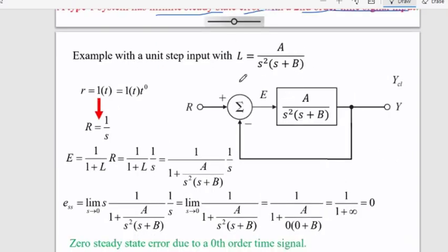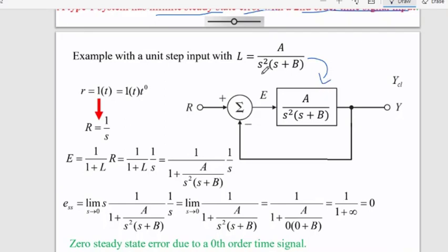Okay, now I have changed this transfer function a little bit. Now we have put s square here instead of s. You can note that, and I will check for unit step again. We want to know the order of this system, so we are applying our step input, which is 1 over s in the s domain, and going through the same procedure. I saw that the steady state error is now 0. This is not clear since we don't know the order of the system yet, because we must get a steady state error of a non-zero finite value.